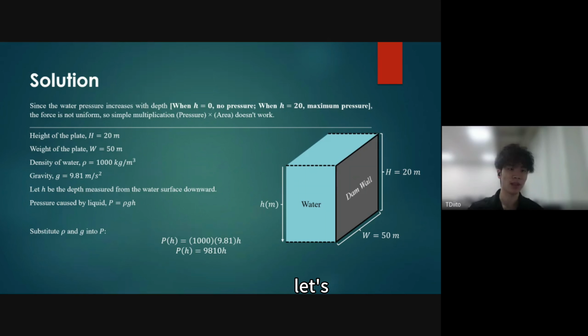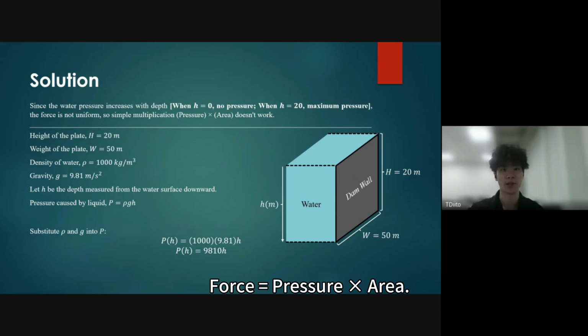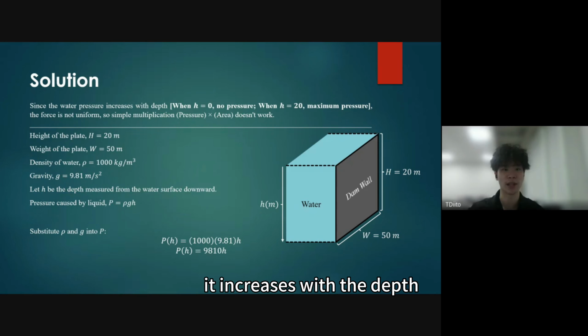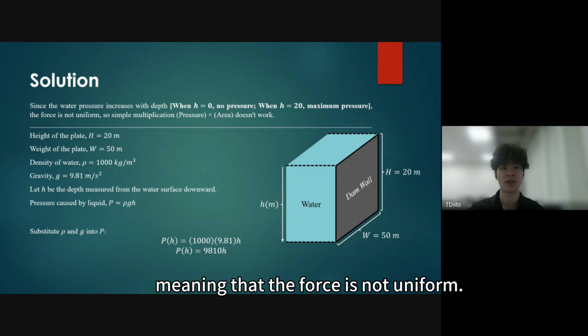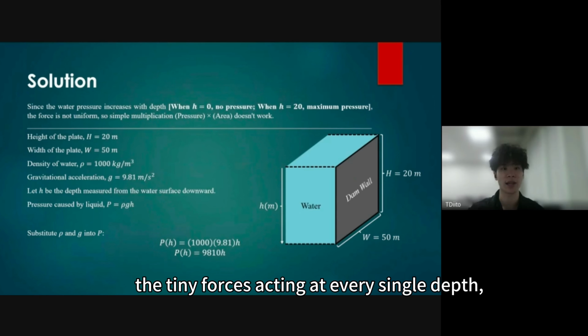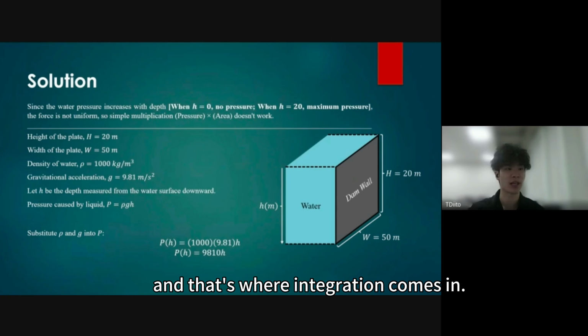First, let's understand why we can't just use the formula force equals pressure times area. This is because the water pressure is not constant. It increases with the depth, meaning that the force is not uniform. Therefore, we need a method to sum up the tiny forces acting at every single depth. And that's where integration comes in.